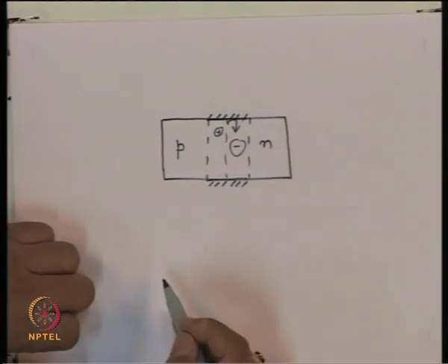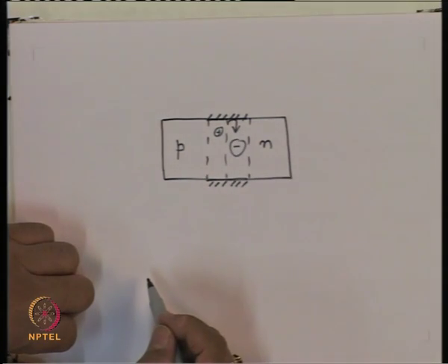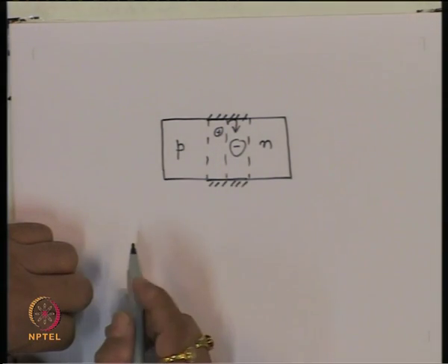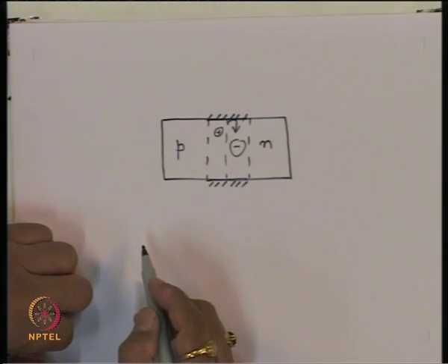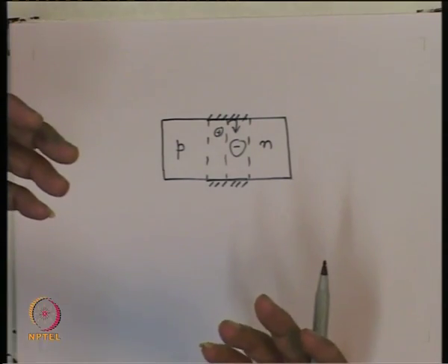So, first thing to note here is that initially when the feedback was not there, as we saw, the efficiency of conversion is very, very small. That means, we have the current which flows into p-n junction, and because of that current the electrons and holes recombine in this region and the photons get generated, but most of the photons get lost and very little light essentially comes out of it. But there was a linearity between the optical power and the current which is flowing inside the device.